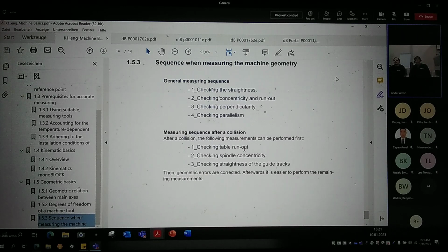So you loosen all screws from the bearing, from the table or from the pallet carrier, and maybe you go with a rubber hammer or a hammer to stress out some tensions of the bearing. Then we can retighten all screws from the bearing. And the most common thing from my experience, if the bearing is not worn out, then the concentricity or the runout will be back in tolerance.